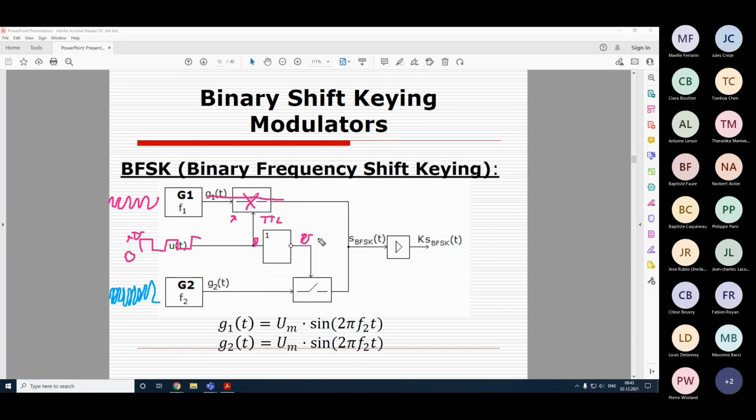It has different voltage levels for 1 and 0. For example, usually we consider that 0 has 0 volts and 1 has, for example, 3.3 volts or 5 volts or even more, but it has some specific voltage level for this symbol. Accordingly, this converts to the specific voltage level which connects this switch, and this signal passes to the output. So at the output, we have either this wave or this wave, depending on what the data signal was and which of these two switches was open.